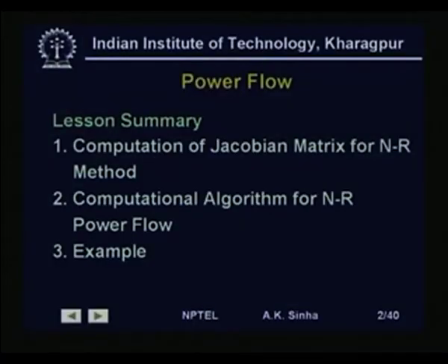In this lesson we will continue with power flow analysis. We will talk about the computation of the Jacobian matrix for the Newton-Raphson method. Then we will talk about the computational algorithm for Newton-Raphson power flow, and we will work out one example for a small power system, how we do a Newton-Raphson load flow or power flow.